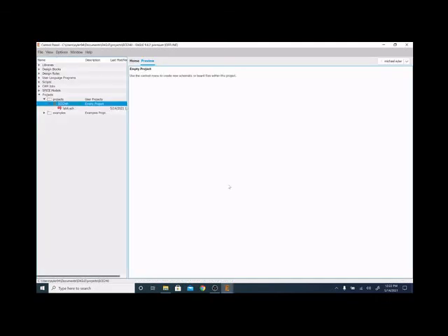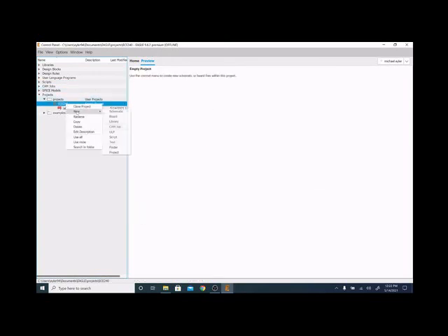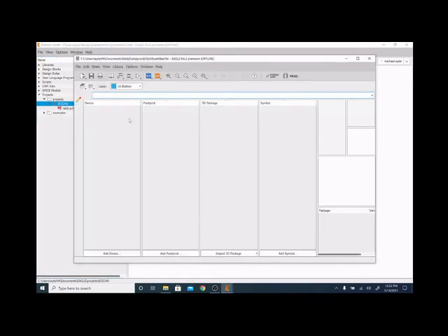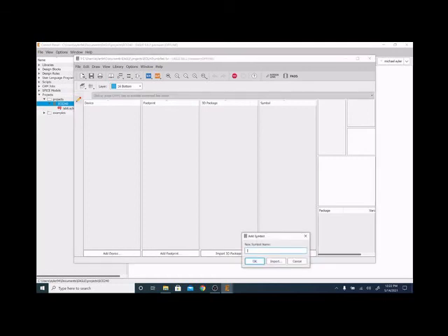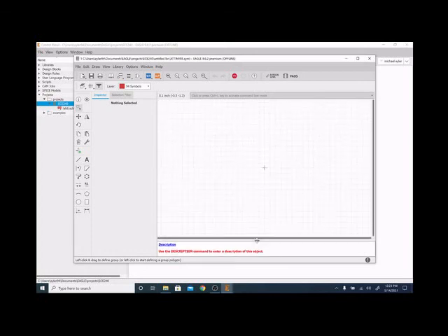All right, now that I've saved and closed my schematic, I'm going to right-click on my project, and you can see it's still active. I'm going to right-click and go to New Library. What we're going to do here is add a symbol and a footprint for the ATtiny85, and then combine those to make a device. So let's start by adding the symbol. The symbol name, we can just simply call the ATtiny85. It's going to say, are you sure you want to make one? Yes, we want to make one. That's fine. And if you scroll, there we go. We can make that window a lot bigger.